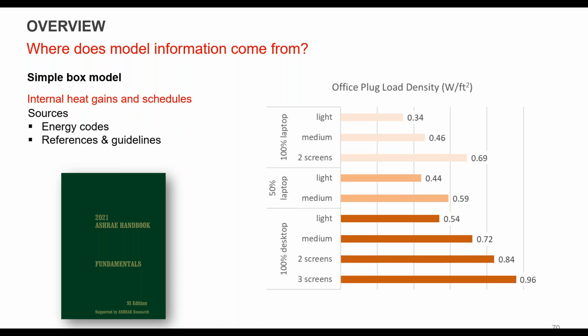If you have old surface mounted fluorescents, and your driver's actually in the space, right at the ceiling, you're probably getting closer to 80 or 90% of that heat load actually showing up as heat gain. And if it's a pendant type fixture, then you're probably getting 100%. So you just have to look at what type of lighting it is, and how it's being installed.